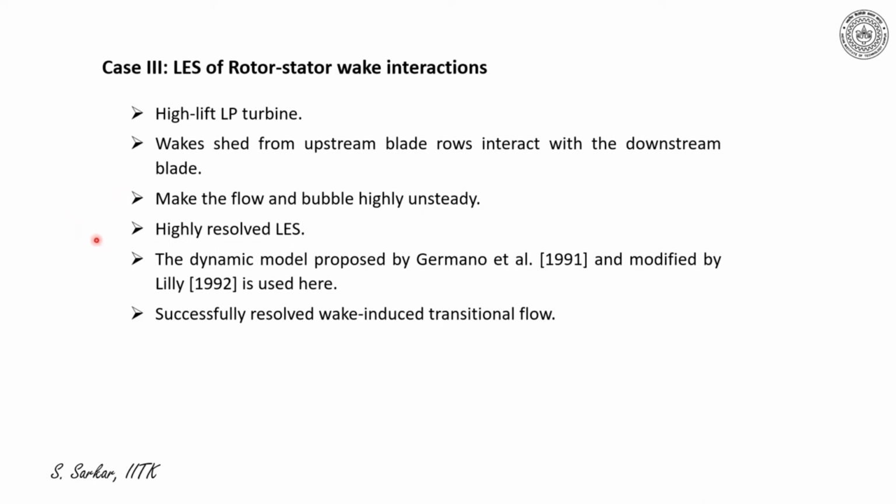I have used here a highly resolved LES. Thus, a refined grid has been used for this case, where the grid number was around several millions within the blade-to-blade plane, and the total grid required to resolve the upcoming wakes and the following blade passage, considering both, was more than 12 million grids. The dynamic model proposed by Germano et al. in 1991 and modified by Lilly is used here for the simulations.